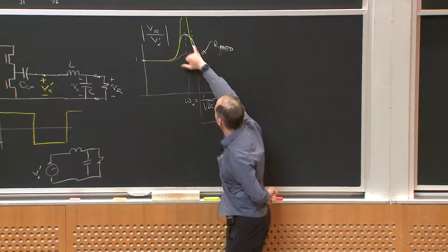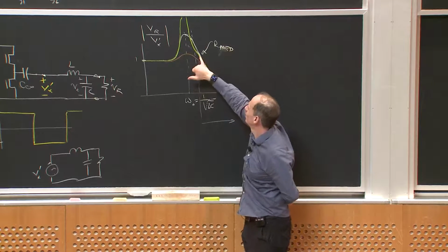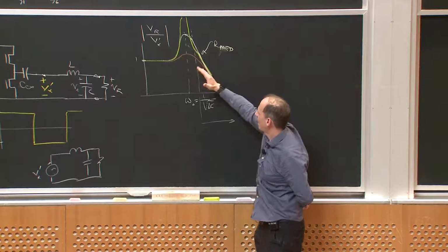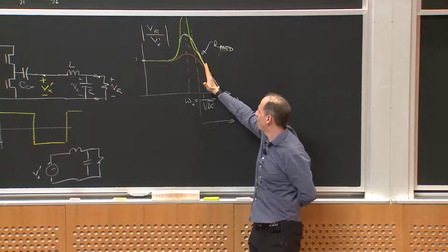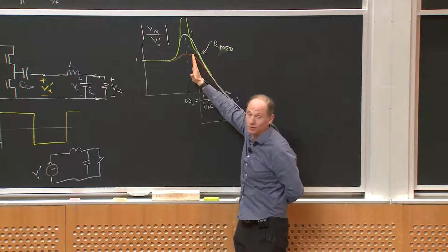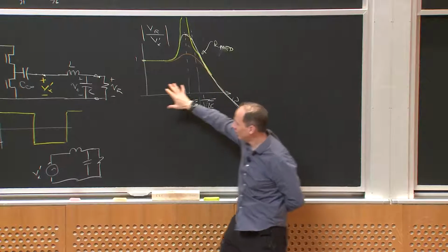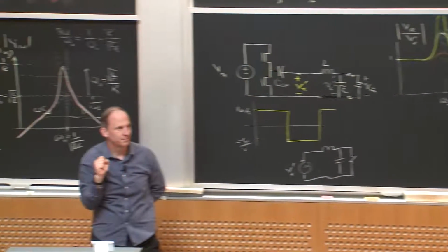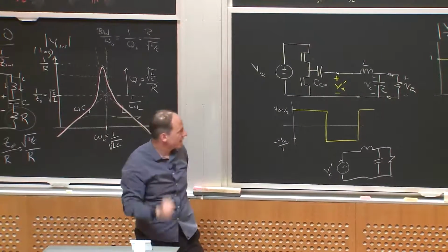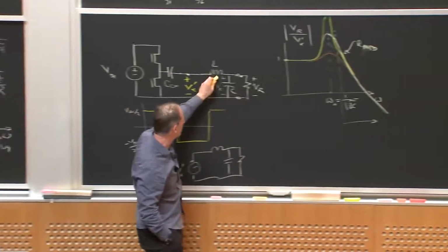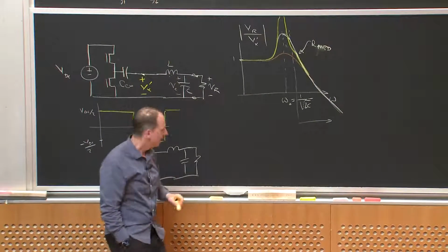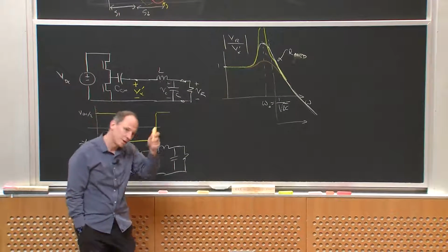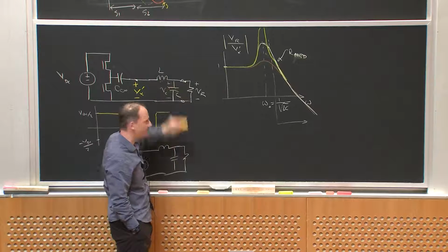And I go from the green curve maybe down to the white or orange curve, and then I can modulate the amount of power in the light by moving frequency. So this kind of network would be at the core of many fluorescent lamp ballast drivers. And we're taking advantage of the resonant voltage gain I can get from this high Q tank. It's particularly high Q when the lamp isn't struck. So sometimes I want the big voltage, even though I have to rate this capacitor and inductor for it.